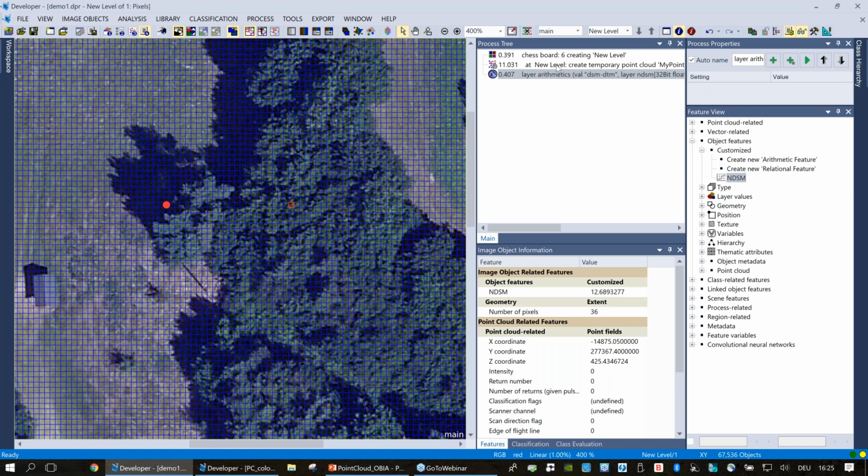Right. So in this case, we had a DSM layer available to us. This DSM came from another source. It could have been a photogrammetric source. Someone created a DSM product in a photogrammetric software, or it could have been derived from a point cloud previously. In this case, I'm showing the example. We have the DSM only available to us as a raster, but I'd like to also have a point cloud. So these rasterized elevation products are typically derived through some of those sources.